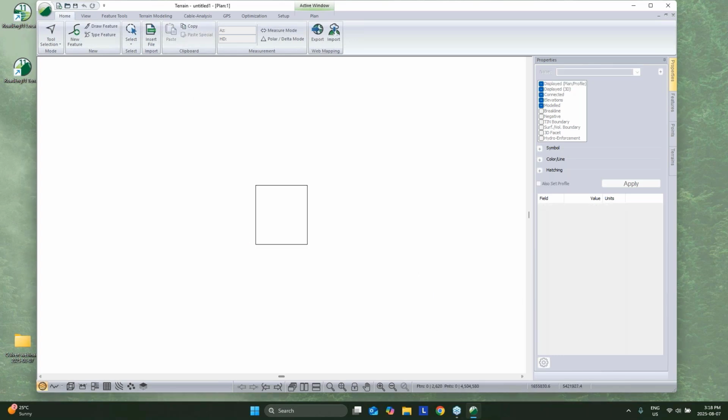Now, it's a DTM, but the raster in our software, we're going to work with a tin regardless of the format. So if it was a LAS file, it would be very similar. If it was conventional survey data, we'd automate that process so we didn't have to connect all the dots.